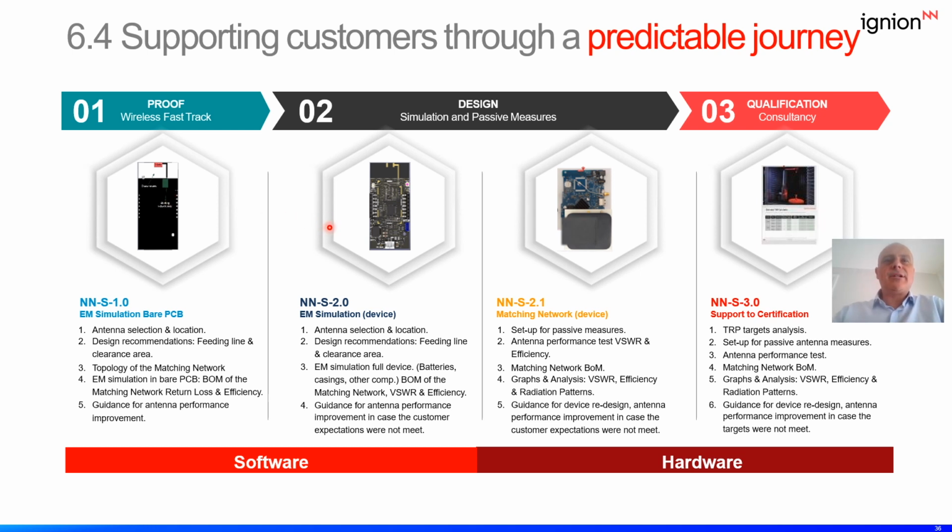A second service, in case you have the mock-up with the components, the batteries, and the casing, and you need to test what the performance will be: we can take those components into consideration and again simulate and provide the best matching network, the best antenna booster, and the results you are going to obtain in terms of S11 and efficiency.